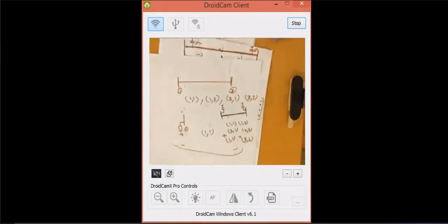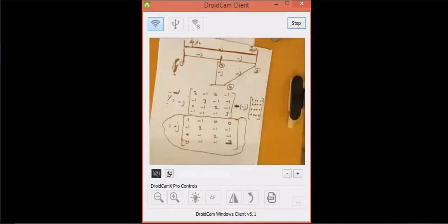Anything connected directly to the bus is going to affect the II element. Anything connected between two buses, I and J, is going to affect the II, IJ, JI and JJ elements in the matrix. I hope this is clear. Clear, Doctor, thank you.